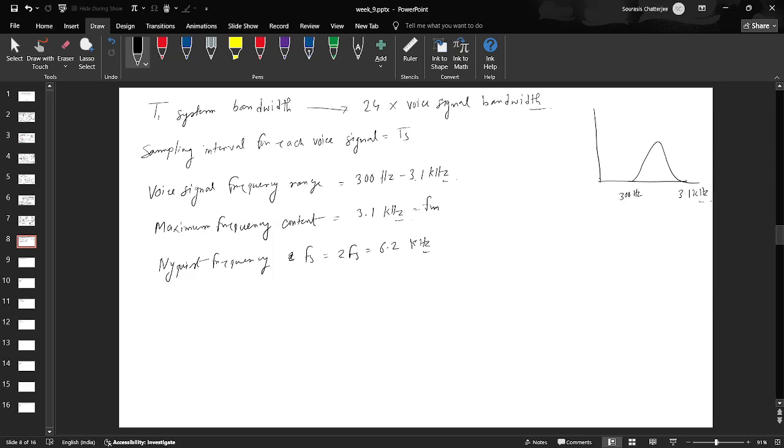But of course that is under ideal conditions. In practice we always need to keep a healthy margin. You cannot go by the borderline Nyquist rate, because that is for the ideal scenario. In practice the ideal doesn't hold, so you should always have a safety margin. So what do you do here?